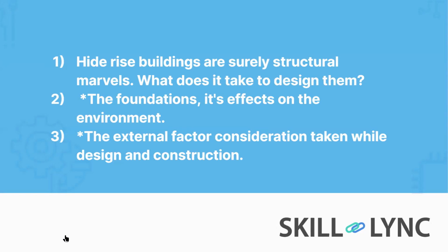Okay, that's a nice statement. High-rise buildings are surely structural marvels. Nice to hear that, being a structural engineer. So, what it takes to design them, this is basically what I answered in the previous question. In terms of the principles of design, it is not much different from any other building. It is only in terms of the magnitude of forces, the magnitude of the structural element sizes. The only additional factor is the heavier wind loads that are going to act on your high-rise building.